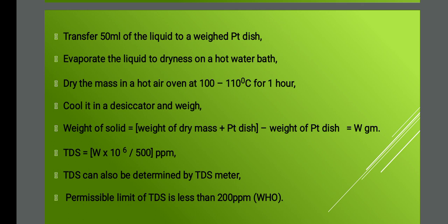This is one way of measuring total dissolved solids. Another one is, you can use a TDS meter. It's nothing but a total dissolved solids meter. We have a knob like a thermometer. If you immerse it in the water sample, it will directly give the TDS value. It's the instant one.